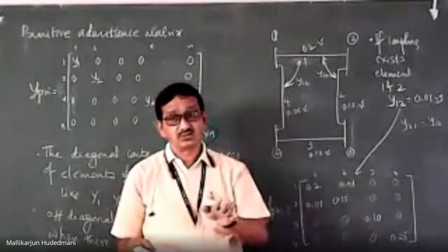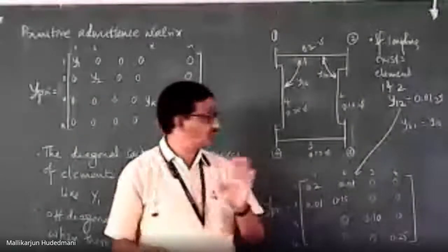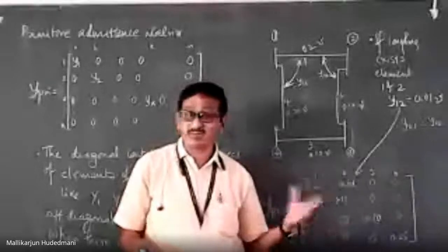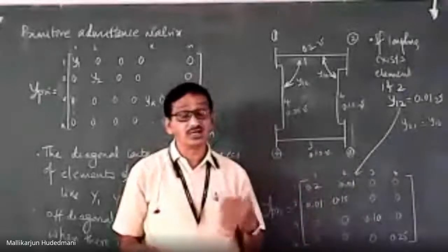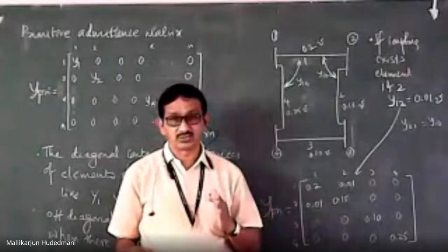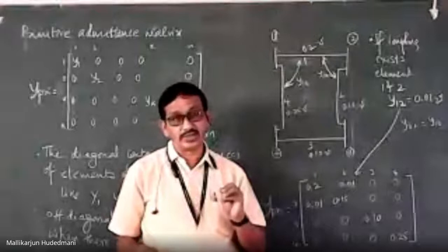That matters. Whether there is a coupling or not, the respective representation should be accompanied in the matrix, because this matrix serves as a backbone for us to represent elemental interconnection into the system admittance bus. So this is called the primitive work one needs to take into account.